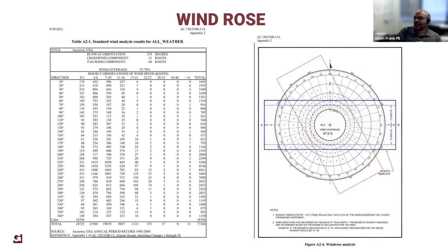Now, if we can't get the 95% wind coverage based on the weather operations, that's when they'll look at constructing a crosswind runway. Hey, do we need to put one in? And again, we'll do the same thing with the crosswind component, see where we can gain more coverage and align that as the crosswind runway. As you can see, I've put that in red. This example didn't really come with something that shows a crosswind component, so I've just drawn that in for discussion.